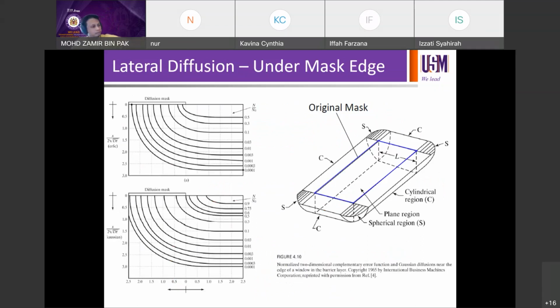Let's try to finish this. Now 11:40. When you run your diffusion process, if you compare to the earlier slide, diffusion versus implantation, we have seen that your diffusion profile tends to go inside and slightly wider, right? On the other hand, implantation will be at a certain depth and more in control of the sites, because it is more accurate. Your width control will be very accurate because you are bombarding the ions into silicon at a specific depth and width, right?